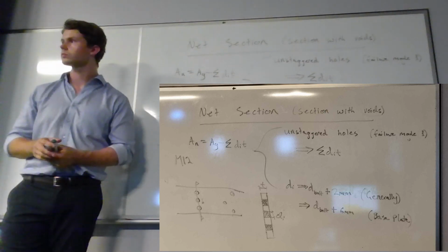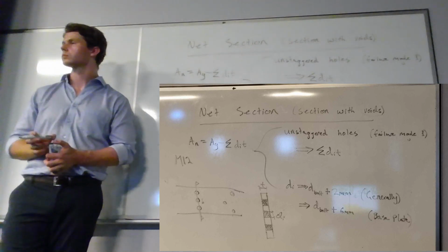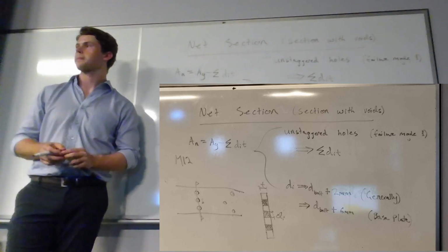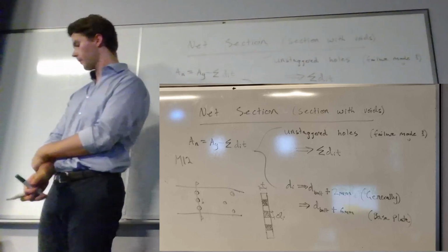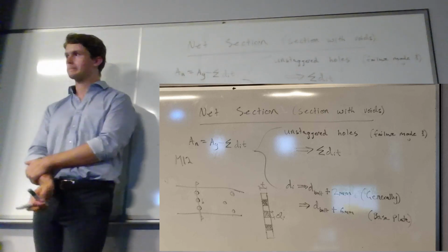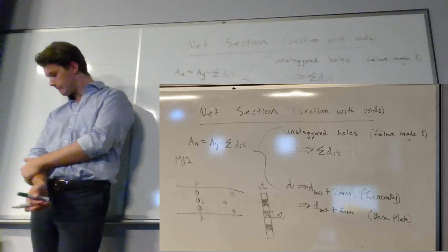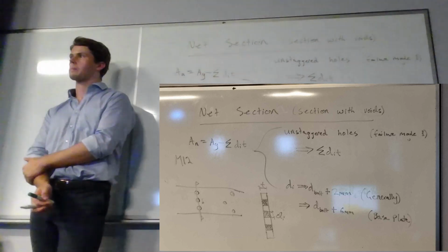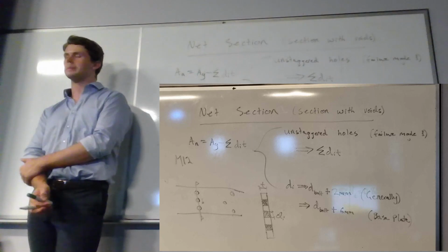One of the other reasons is whatever you're attaching to your base plate, maybe a column. Members on the floor generally have the largest load on them, because they are withstanding the load of everything above, so they are subject to more movement. You don't want a very tight system at the bottom that doesn't allow some slack from a construction point of view.